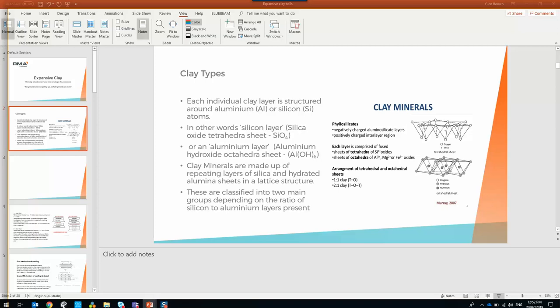Here's a couple of examples. I've seen a lot of stuff over the years that makes an appearance. Waffle pods get a surge every now and then. We only use them for M sites, the main reason being the whole system is flawed. It's all above the ground on a crusher dust bed, and if you don't get the drainage 100% right, you're just inviting water to go straight underneath the perimeter of the slab, and it just ends in tears.